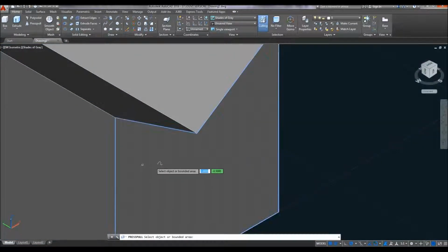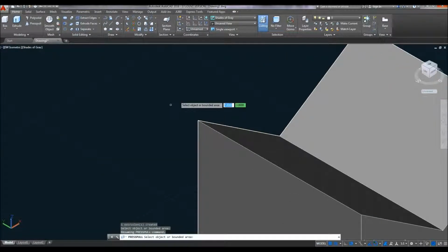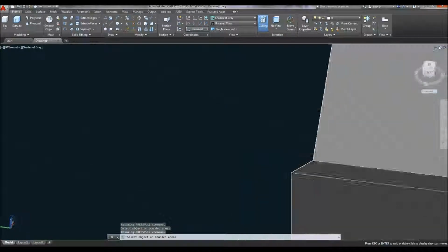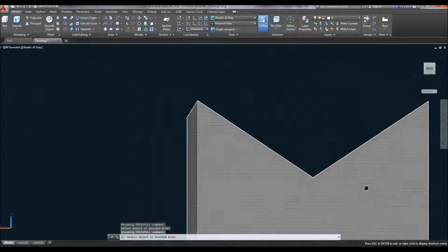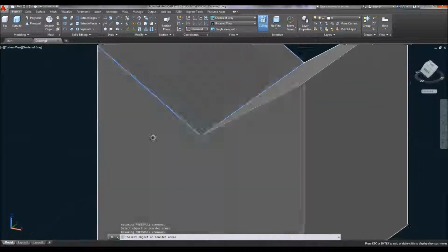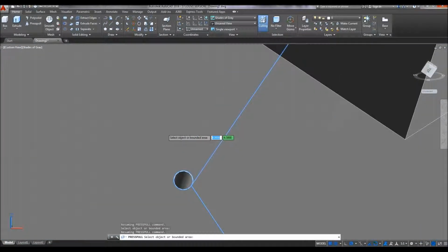If you're trying to make a piece of pipe that has a hole in it and you only want it going through so much, you type in that amount, and it will go through that amount, and only that amount. It's very exact, and for 3D printing, I'm pretty sure this is in inches, so you might want to be aware of that. In my thing, I was just doing it by feet. I was saying it was feet, but for scaling and stuff, you can have it feet, but it actually is inches.